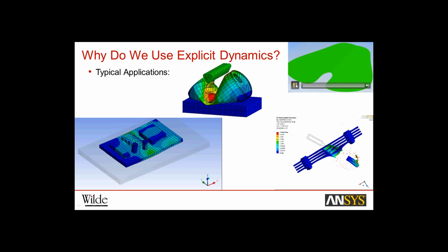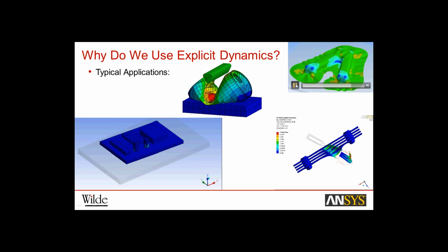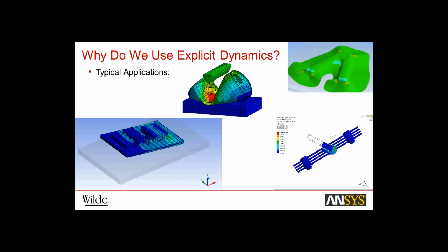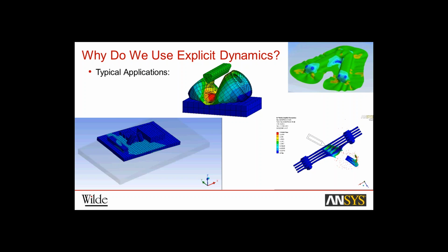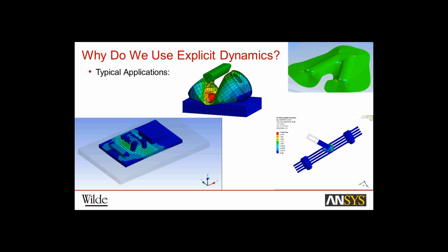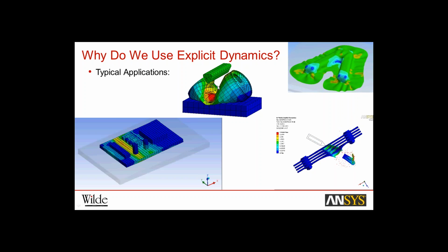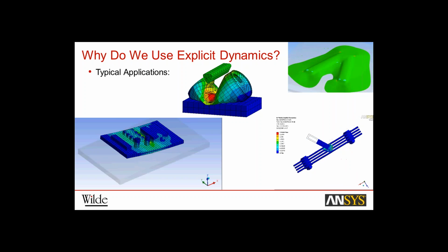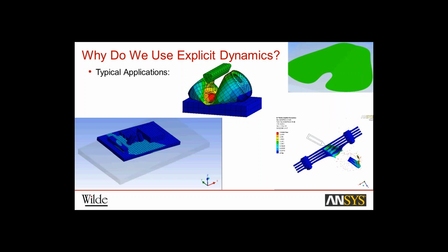Top right, we've got another application for Explicit STR, which is metal forming. So here we're pressing a sheet, looking at the highly nonlinear behavior of the material, and we can include spring back by releasing the load and seeing what happens to the resulting part. And then finally, the soda can, we're looking at nonlinear buckling with plasticity and very complex contact conditions where we can't predict what will touch and what will interact with each other after load's been applied.